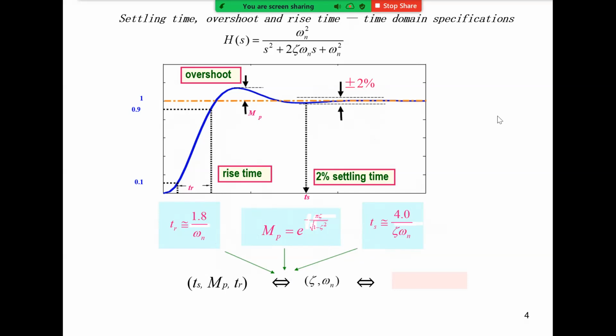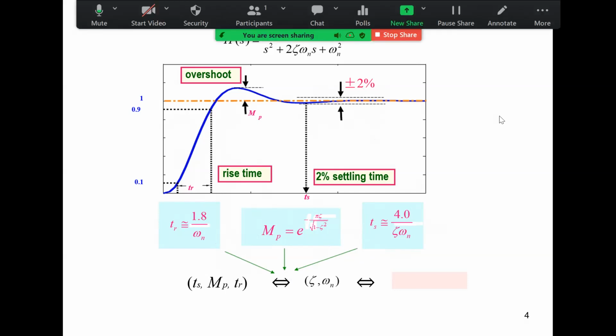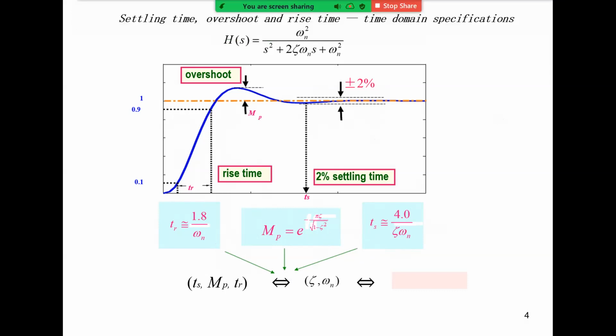Of course, when you do your mini project, if there is no overshoot, which I think the overshoot ratio is below 10%, then it satisfies the requirement. You have those requirements, so you figure out what are the appropriate values of the damping ratio and natural frequency such that it can meet all the requirements on the overshoot, the settling time, or the rise time.